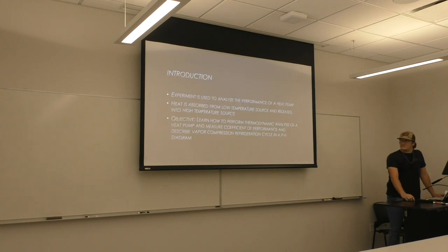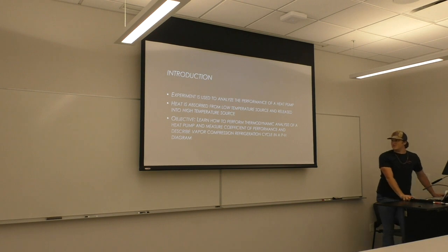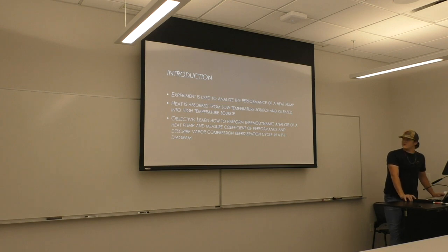A little introduction. The experiment is used to analyze the performance of a heat pump. The heat is absorbed from a low temperature source and released into a high temperature source. The objective of this experiment is to learn how to perform thermodynamic analysis of a heat pump, measure the coefficient of performance, and describe the vapor compression refrigeration cycle and pH diagram.